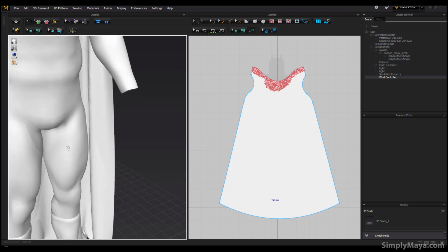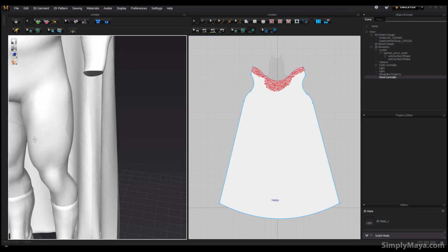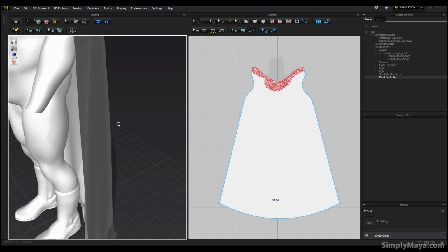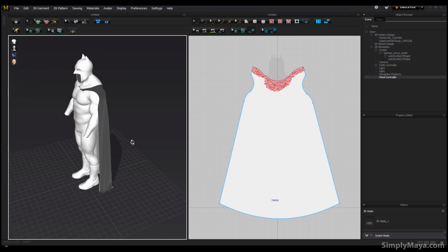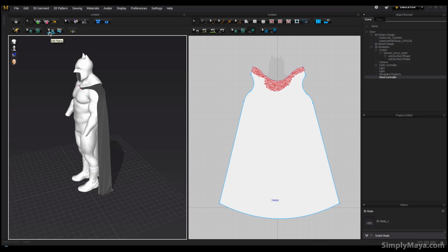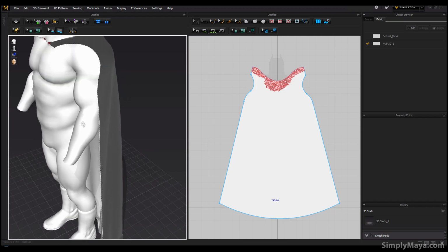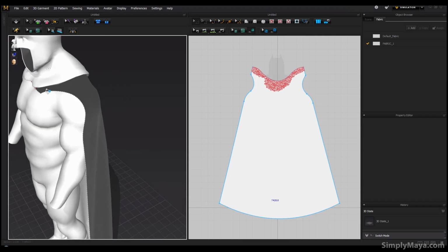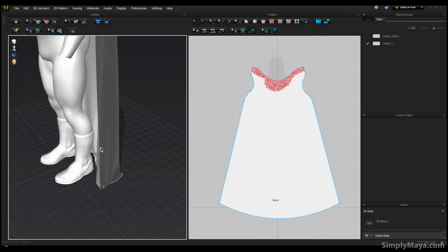So if you were to look at this edge corner on, like most cloth in 3D, it's actually razor sharp. And cloth normally has some sort of edge to it, so we're going to put a piping material around. Now in Marvelous Designer this is very, very simple. You go up to here and you've got your edit piping and then your add piping basically. So you'll see all around the outside of our cloth comes this dotted line, and that's where we can put piping.